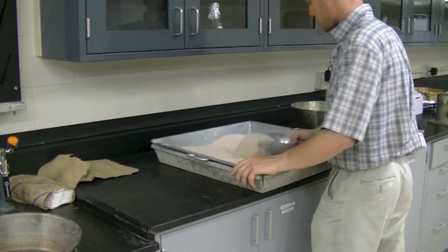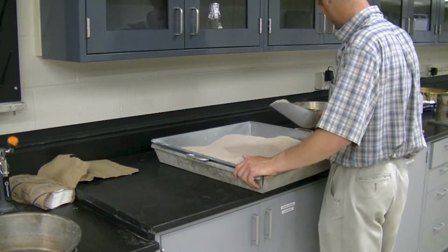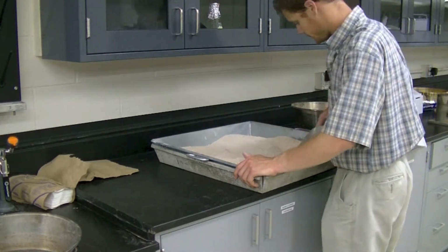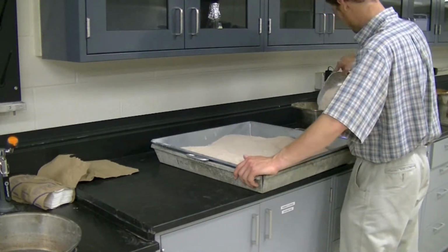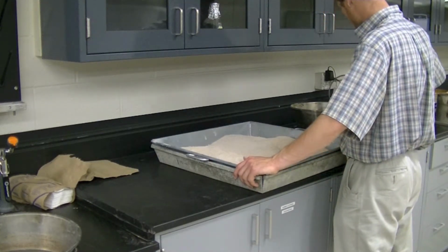After mixing the finer fraction thoroughly, weigh out approximately 5 representative pounds in a bowl. Tare the bowl and transfer 5 pounds into it. Repeat this step 3 more times to obtain 4 subspecimens, all containing even amounts of soil.